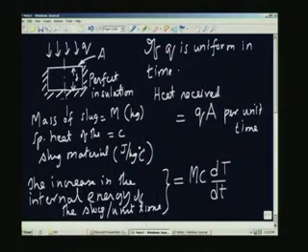If you go back to the previous note here, heat loss may actually take place all around the region surrounding the slug in all directions. But what I will do is equate it to an equivalent heat loss per unit area from the top surface. I will base it on the area A, which is receiving the heat.